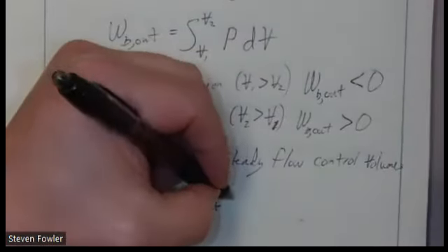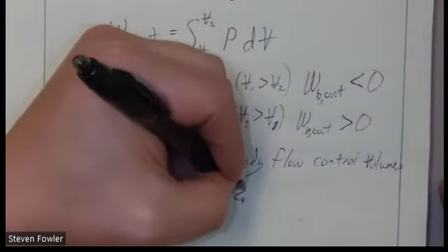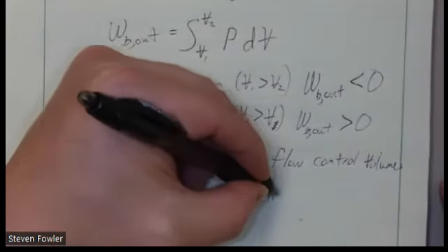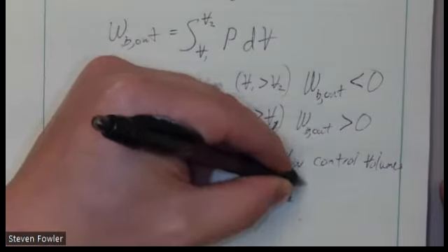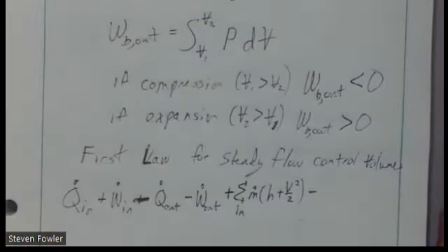And then, because it's a control volume, I've got the energy of the mass in. I'm going to do a summation. Let's do a general form here. Let's say summation across all of the inlets, m dot times (h plus V squared over 2). I'm not going to include the potential term because, as we've seen, we normally just neglect it. There is a potential energy here, but it's very rare we even consider it. It's nothing I would test you on. I wouldn't put a control volume on an exam where there's a huge potential energy difference. It's just not practical for most situations. But you can have an enthalpy change and you can have a kinetic energy change.